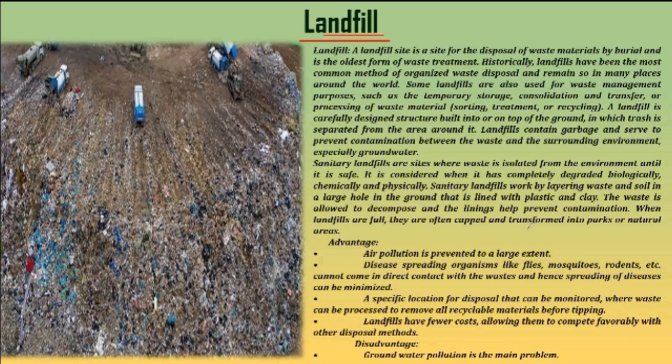So historically landfill has been the most common method used in many places, though according to me open dumping is also very common, right? Because it is very, very cheap. Some landfills are also used for waste management purposes, that is sorting, treatment and recycling. Now a landfill is designed into or on top of the ground, in which trash is separated from the area around it. Landfills contain garbage and prevent contamination between the waste and the surrounding environment, especially groundwater.